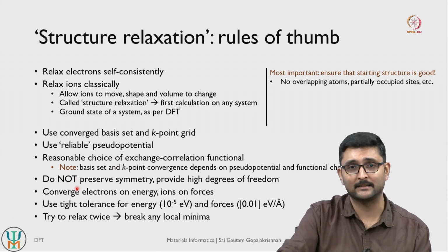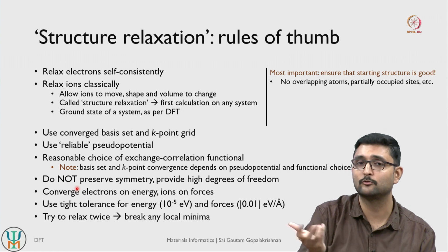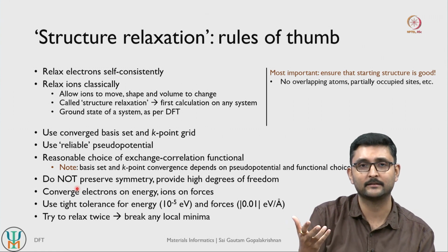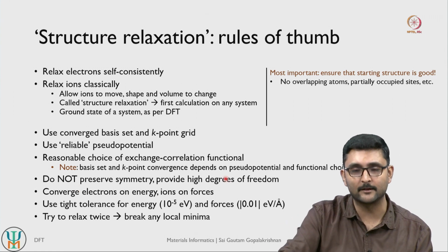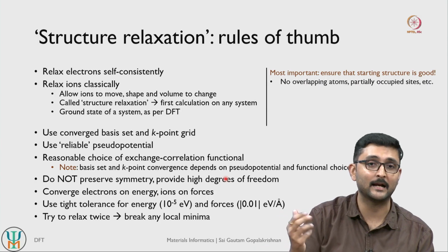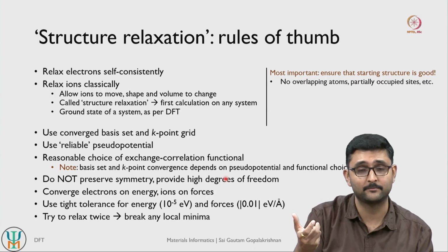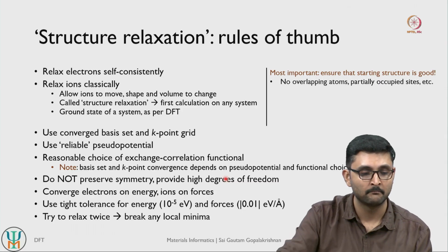Do not preserve symmetry, as I mentioned before. When you start off with the structure, do not preserve symmetry, see what the structural relaxation actually gives you. So try to provide as high degrees of freedom as possible and see if you recover back the same structure that you started with, right.